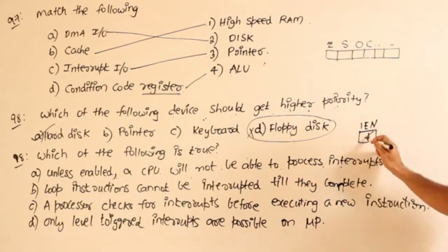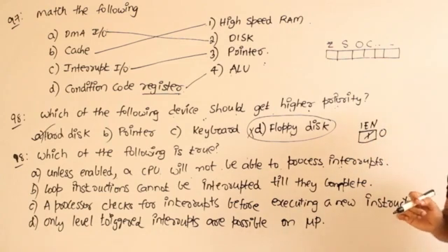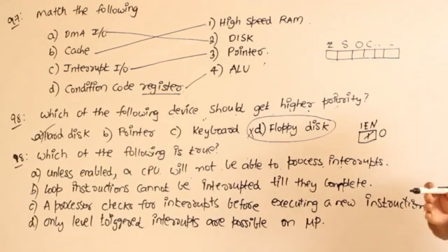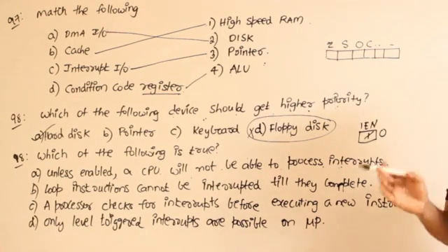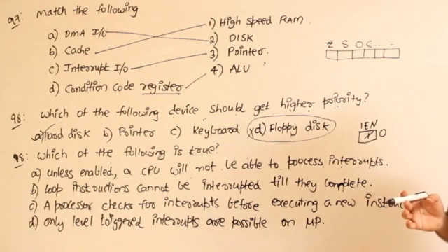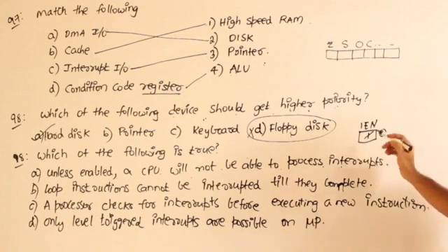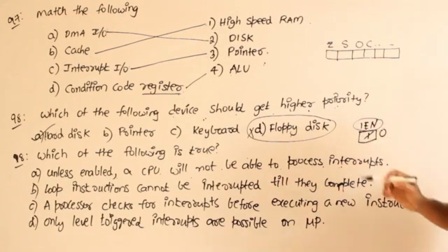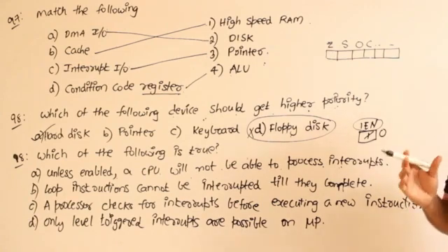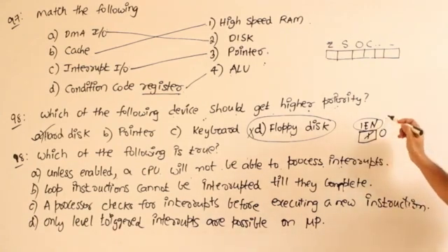In case this flag is 0, even if there is an interrupt, we will never look at it and we will never enter into the interrupt cycle. We finish the execution of an instruction and we get into the execution of the next instruction without getting into the interrupt cycle and interrupt service routines at all. So this particular flag, every computer will have such a flag.